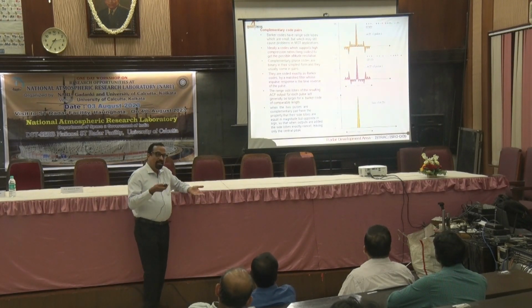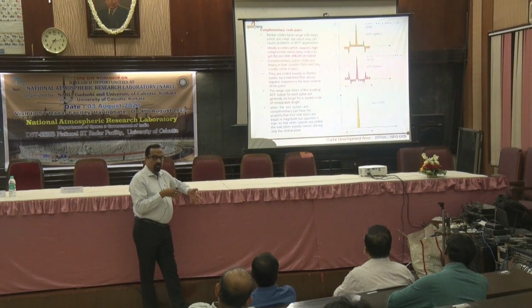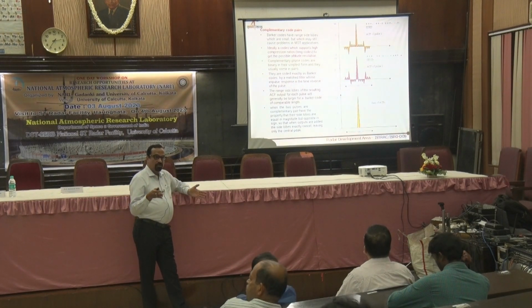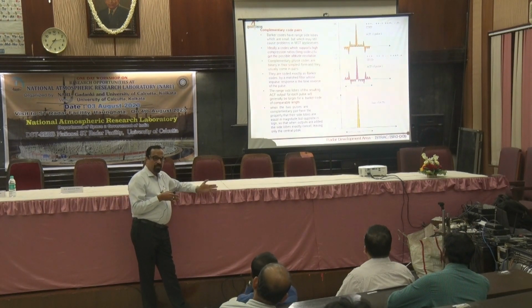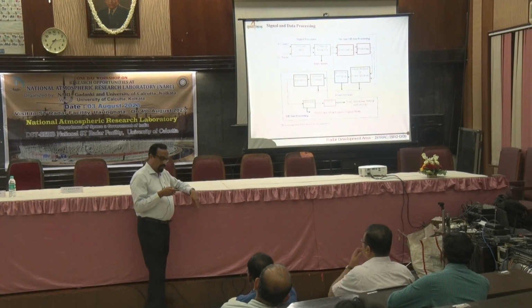So it is nothing free in that sense, what we are doing comes with some concern also. Essentially, when I am using, say, a 500 Hz transmission, with repetitions of 500 Hz, I add two pulses together. Effectively the time is added two times, so I reduce my bandwidth of observations to 250 Hz. That is one point which has to be remembered when doing this kind of thing. Okay, go to next. These are the total blocks which come in the signal processing area.